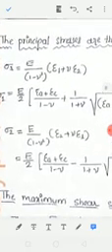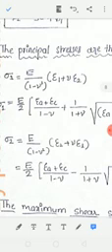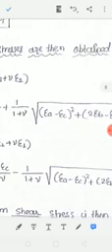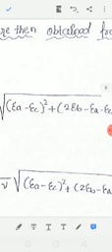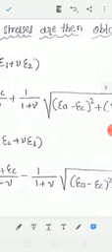We will get equation number 8: sigma 1 equals E divided by 2 times [(epsilon a plus epsilon c) over (1 minus mu) plus 1 over (1 plus mu) times the square root of (epsilon a minus epsilon c) squared plus (2 epsilon b minus epsilon a minus epsilon c) squared]. Okay, the whole square, so you will get this equation. Now epsilon 2 and sigma 2 you can also substitute the same way, and the maximum shear stress you will also get the same way. Similarly you have to substitute in the equations we have determined.